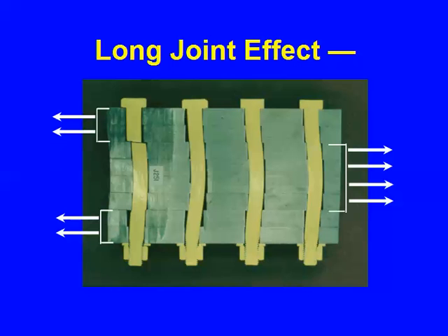We see that one fastener has failed. There's one shear plane failed here, and then the test was stopped. With this number of bolts, you can stop the test when one has failed if you're very, very careful about it. Okay? I'm going to look at another illustration before I explain the features that I want.